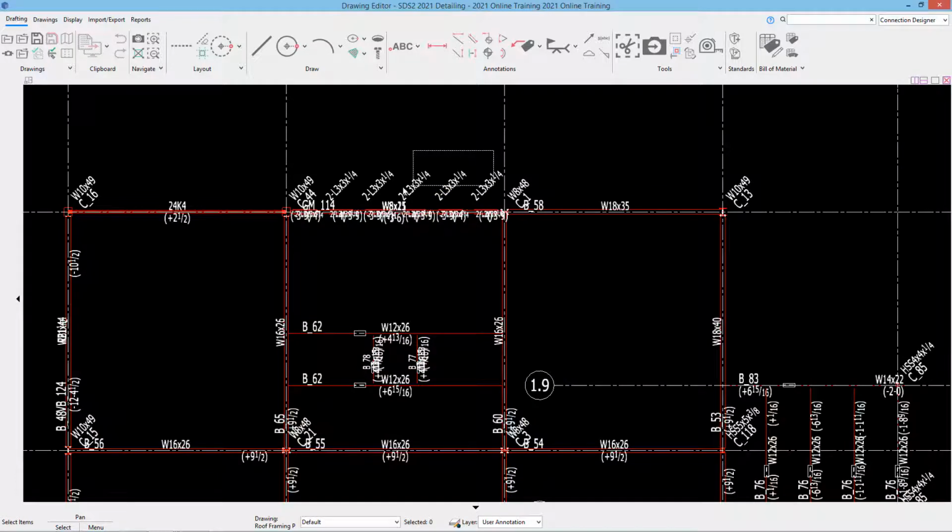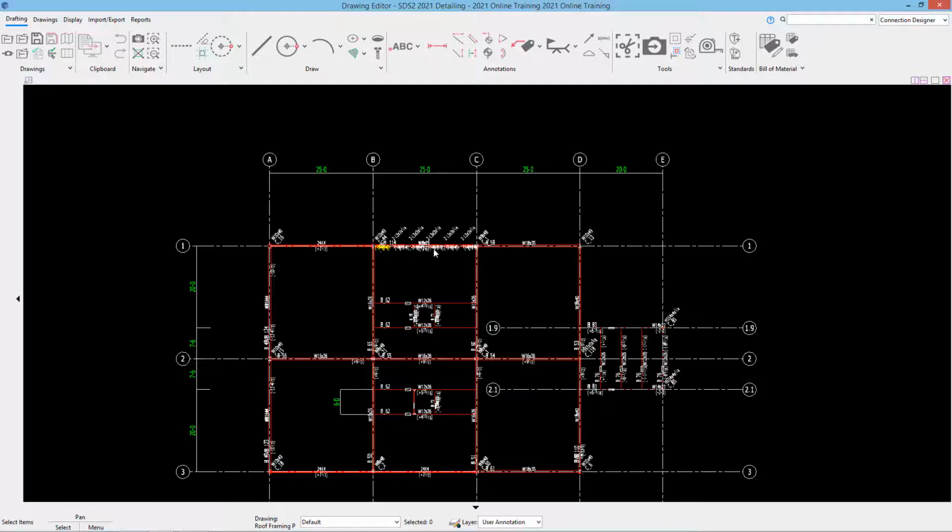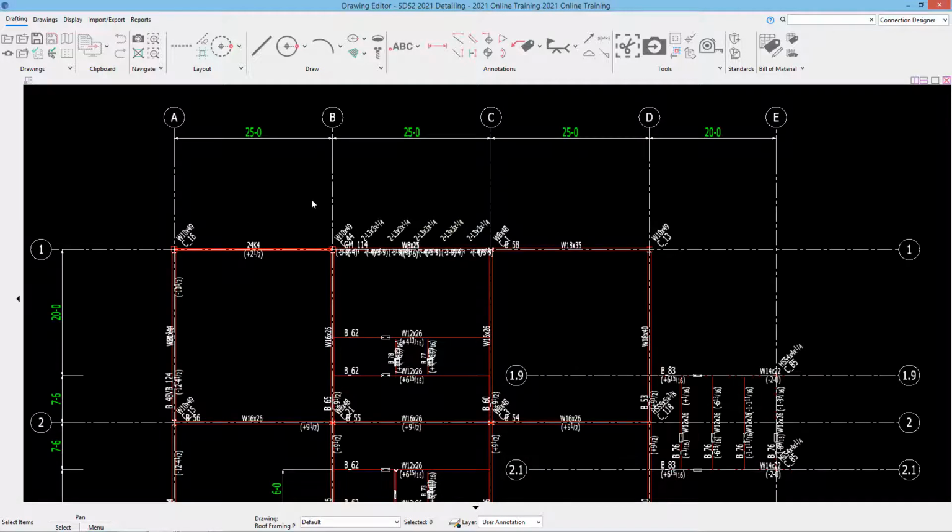Again, I can come in here, delete out some of those using either the erection view cleanup tool or my different options of selecting, deleting, or just editing. So again, I'll show just how to delete or hide just these vertical braces that are part of this group member. For this, I'm going to use my erection view cleanup tool.